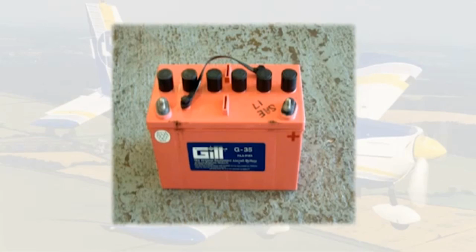Secondary cells work on the same principle as primary cells, but the chemical energy in the cell can be restored when the cell has been discharged by passing a charging current through the cell in the reverse direction to that of the discharge current. In this way, the secondary cell can be charged and discharged many times over a long period of time. During charging, electrical energy is converted into chemical energy, which is retained within the battery until it is once again discharged.